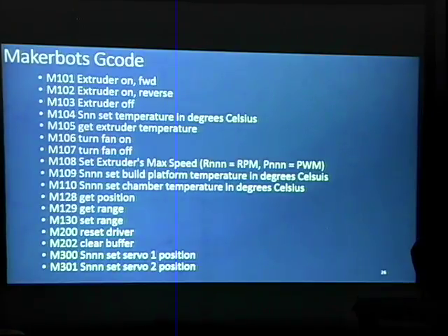First thing to know about MakerBots, they do use G-code. What they do, though, is they have a very weak processor on the board. They've decided not to dedicate processor resources to actually interpreting G-code, even though the processor is capable of doing that. Instead, they compile that code down to almost a serial bit stream. That serial bit stream is faster for it to interpret, so it's able to print faster and keep up at the processor side, despite the fact that all the commands are the same.